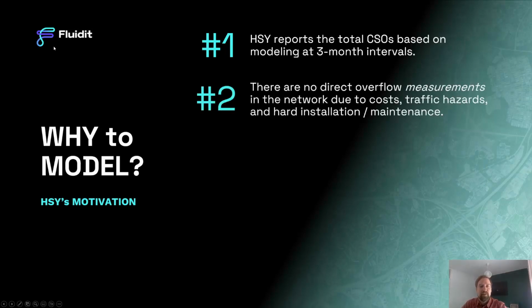It's because there are no direct overflow measurements in the network, and there are several reasons: the cost, but more so the traffic hazards and hard installation and maintenance. Often these overflow locations are in the old part of the city, in heavy traffic areas where it would be very dangerous and also complicated to install any actual measurement devices. So that's why they use simulation software to simulate and estimate the overflows.